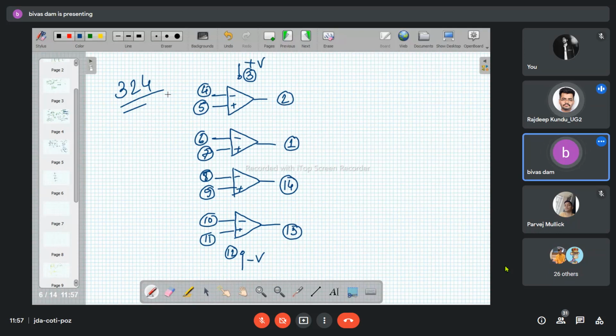Sir, why this naming? It is one standard practice. I do not know why. For any such 14-pin quad IC, this is the standard practice I have seen. Okay, sir. For all 14-pin ICs like this? No, not for all, but for this op-amp and comparator category. Okay. Sir, one more thing, plus minus VCC to all of the op-amps, right? Plus minus all of them.